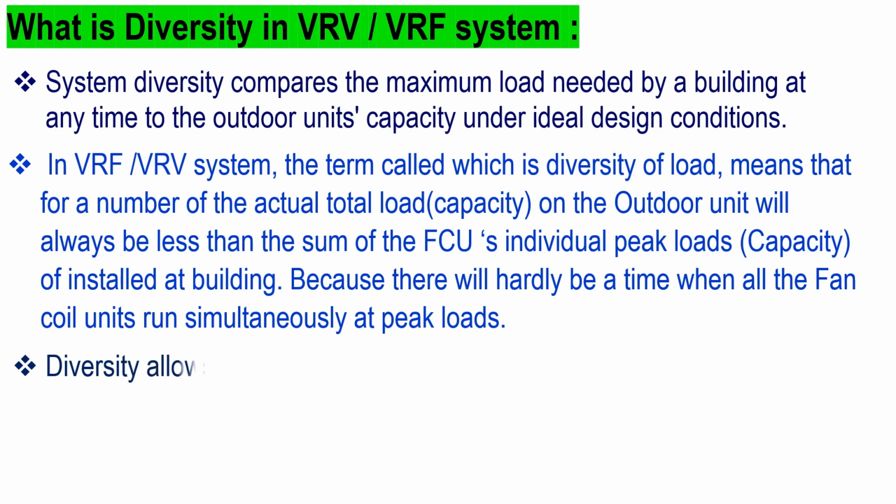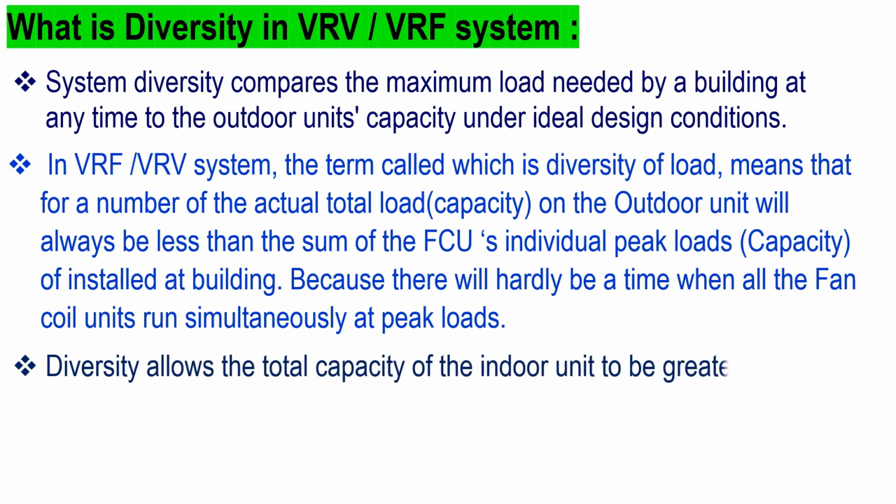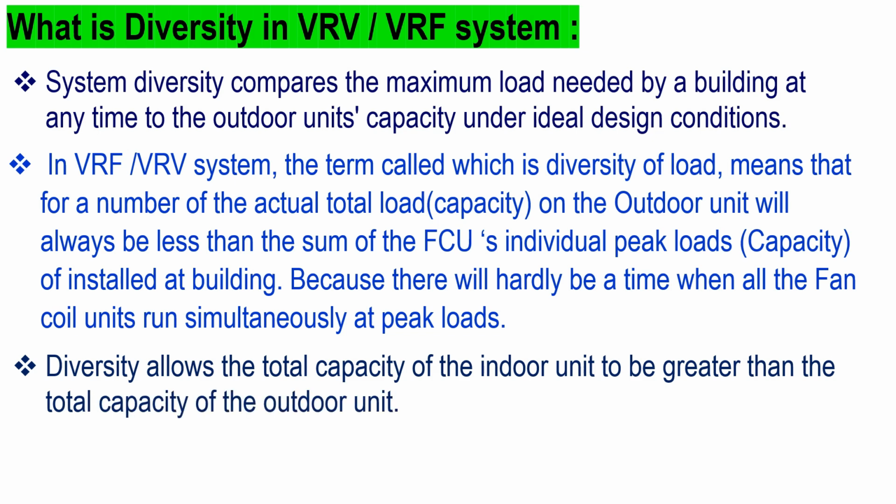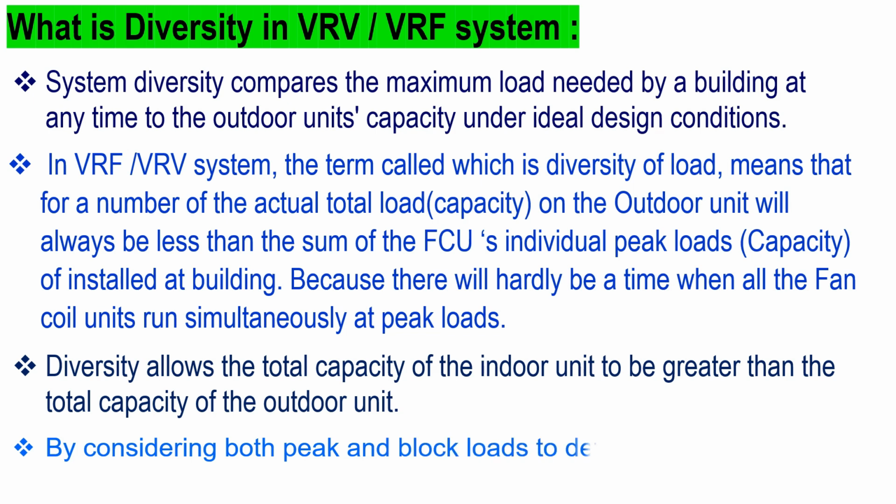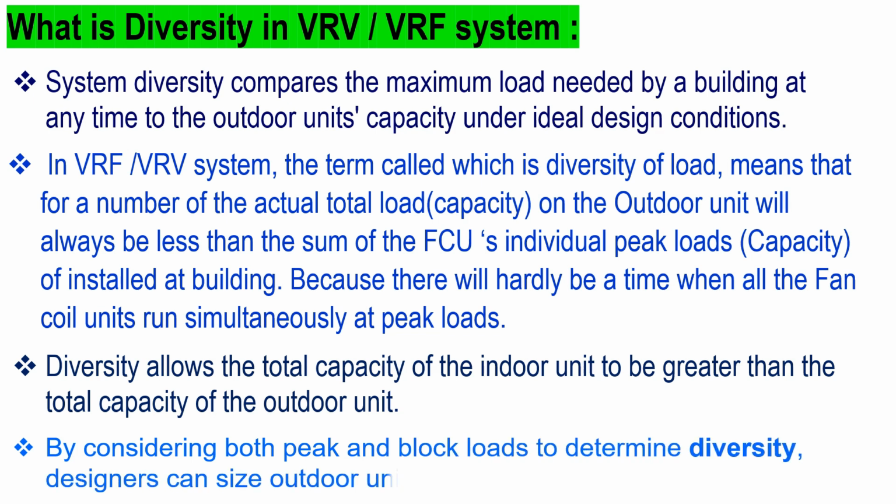Diversity allows the total capacity of the indoor units to be greater than the total capacity of the outdoor unit. By considering both peak load and block loads to determine diversity, designers can size outdoor units correctly without oversizing.